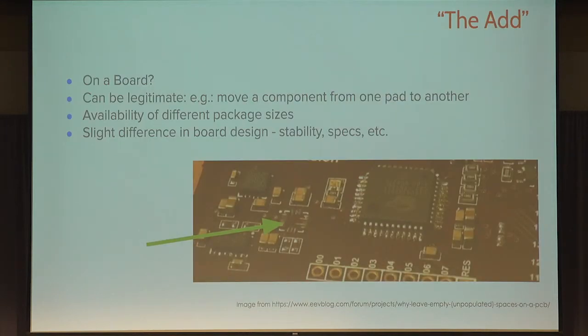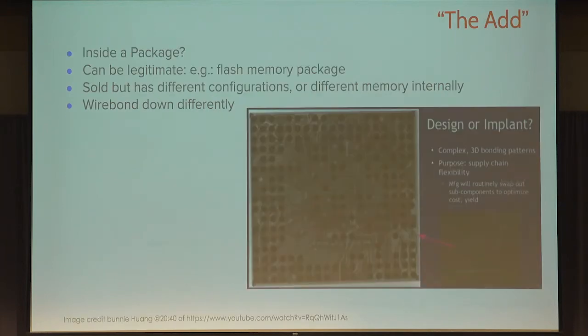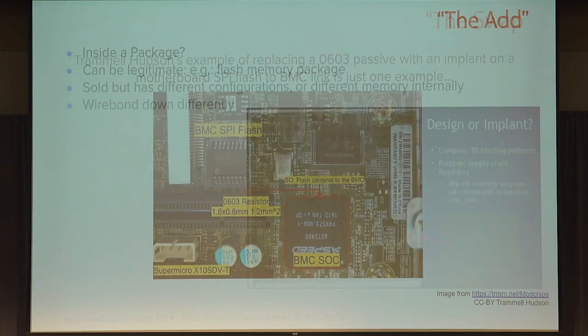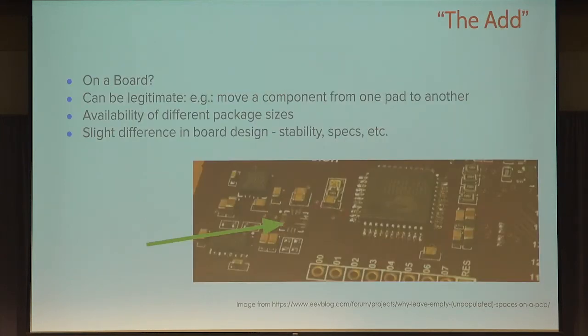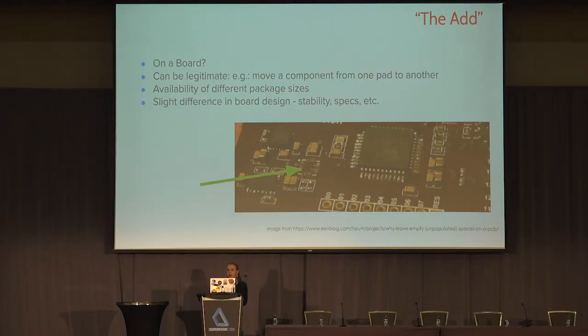All right, so the add is a different type of technique, right? You have the sandwich, and you have the add. The add would be what the SuperMicro case was alleged to be: an addition to the board. However, the issue with this is that it can be a legitimate add, right? You can move one component from one pattern to the other to save costs. You would replace a component with a different one that has similar functionality that also reduces costs. There are different package sizes available for certain things, and depending on the logistics of that manufacturing plant, only certain ones might be in stock. However, this would differ from the original spec. Still, it's become almost prevalent across different manufacturing firms that these replacements do happen.